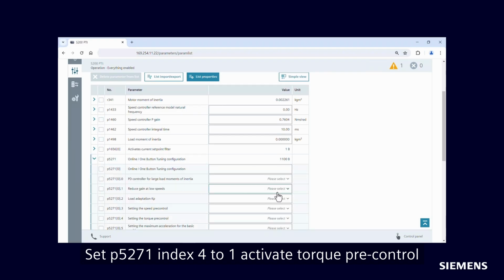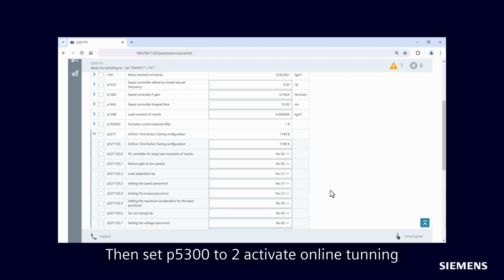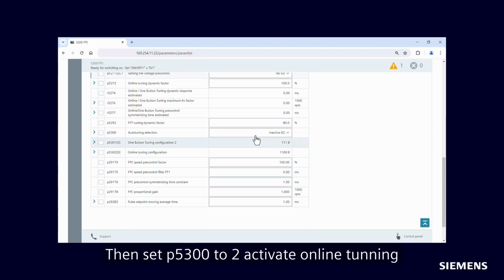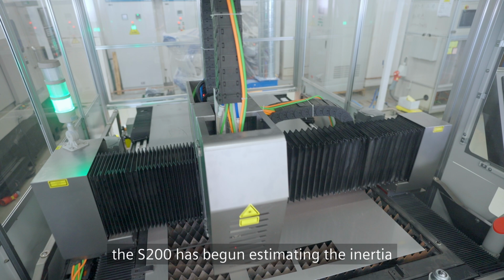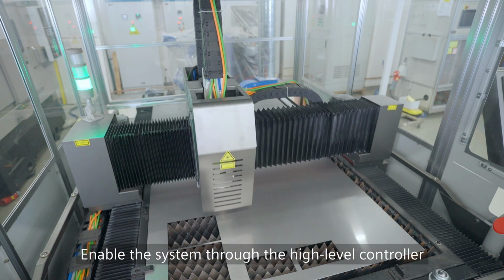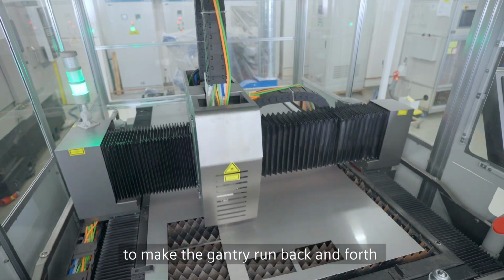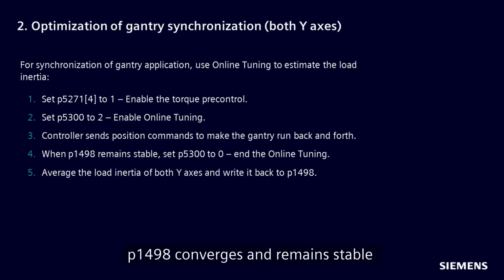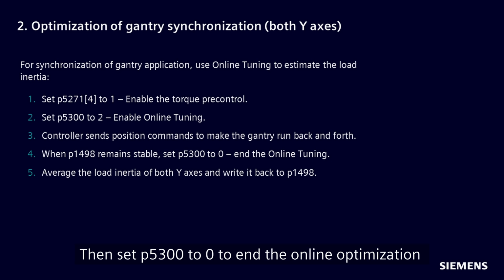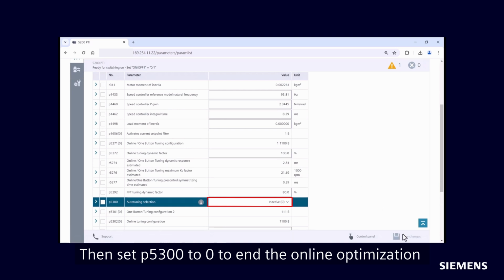Set P5271 index 4 to 1, activate torque pre-control. Then set P5300 to 2, activate online tuning. At this point, the S200 has begun estimating the inertia. Enable the system through the upper controller, and send position commands to make the gantry run back and forth until the value of the load inertia parameter P1498 converges and remains stable. Then set P5300 to 0 to end the online optimization.